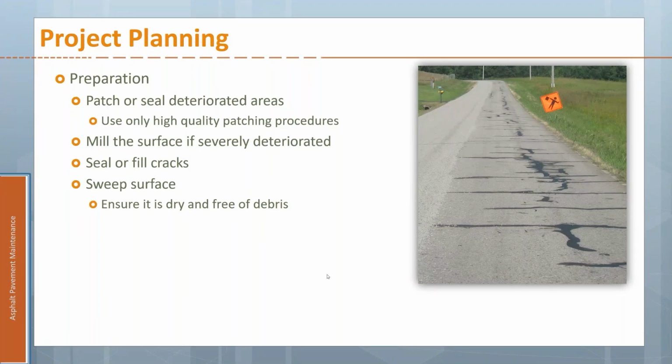If you're trying to cover up a surface that's really deteriorated, you may want to mill that to get down to something that's fairly level, seal any cracks, fill those before you start, and then make sure you sweep the surface and get it nice and dry and clean.